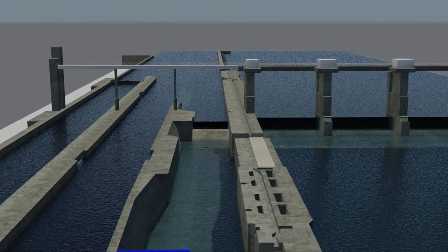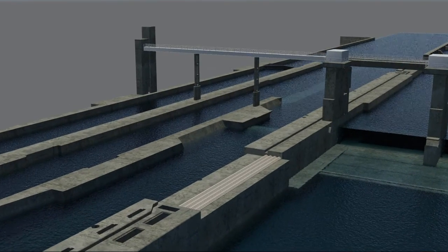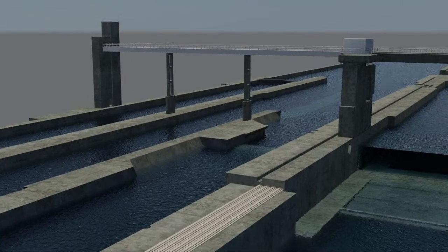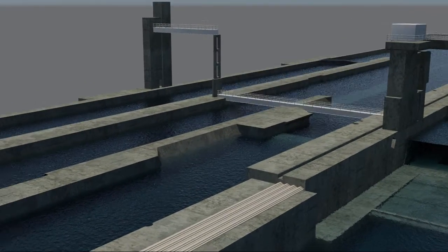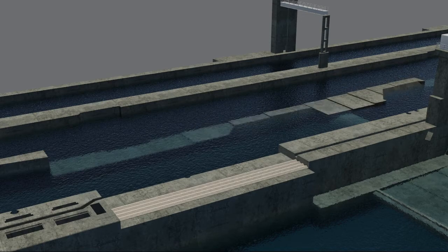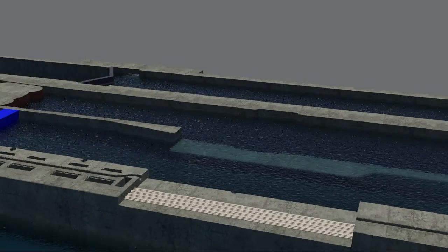We then proceed to breach the fixed crest weir and allow the chamber to fill. After the weir is breached, we can partially demolish the footbridge and demolish original river wall monoliths OR 31 through OR 41. At this point, temporary power and dam controls should already be in place.